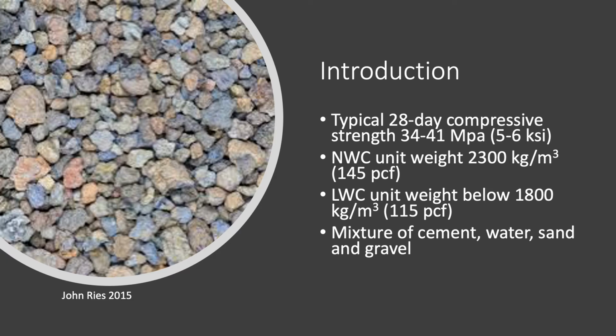Typically, a concrete mix is about 10 to 15% cement, 60 to 75% aggregates, and 15 to 20% water. Internal air in many concrete mixes may also make up another 5 to 8%.